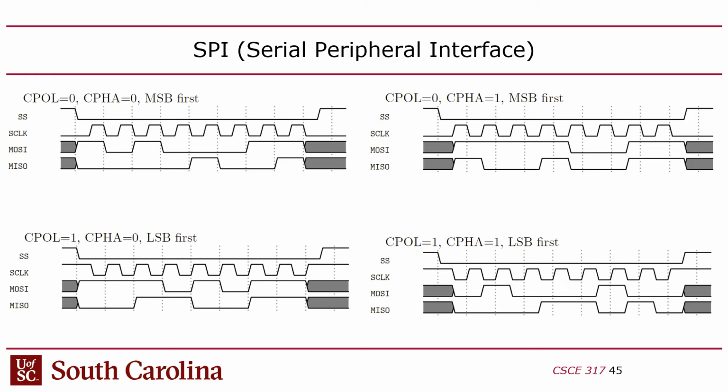Oh, one more thing. Sorry, we kind of stepped on this a little bit, so let me just introduce these. These are timing diagrams. Have you guys ever seen these before? Okay, so a timing diagram, just so everyone's on the same page. This is a plot where the horizontal axis is time, and the vertical axis is, in this case, just binary signals. If you're high, it's a 1. If you're low, it's a 0. Now you might say, what are the dotted lines for? The dotted lines are just a way to establish a correspondence between different signals in here.